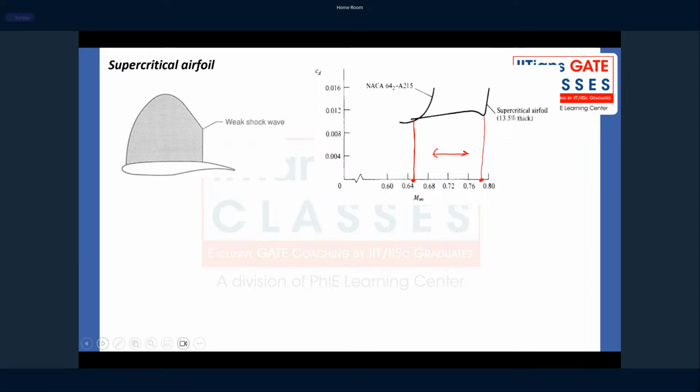Now, why do you think the supercritical aerofoil has a flat top, and why does it have a highly cambered trailing edge? Because the top is flat and you have a curvature in the bottom, for 60% of the distance there's a negative camber, right?